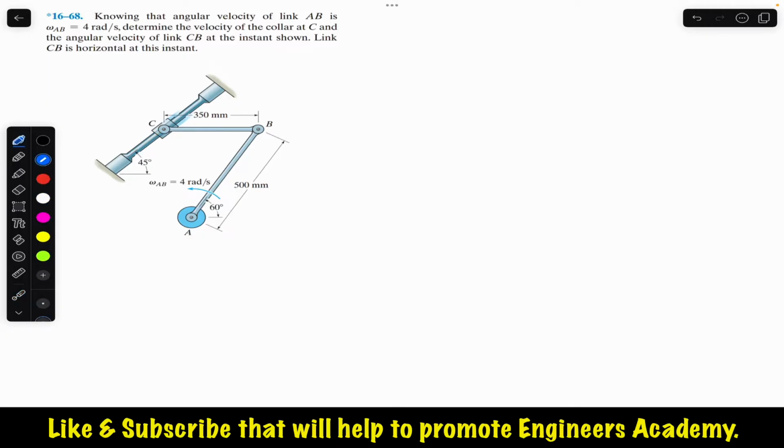Let's say this is link AB. So this red line represents link AB. As we can see, this point A is stationary, so the velocity of B is only due to the angular velocity of this link AB, and that velocity will be perpendicular to this link since this point B is revolving about that point A in a circular path. So the velocity of point B will always be tangent to that circular path, or we can say that the velocity of B will be making 90 degrees with link AB.